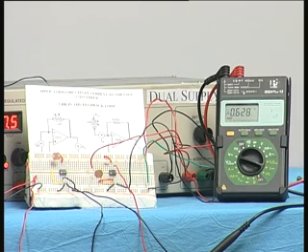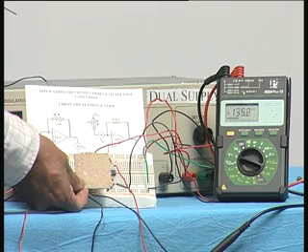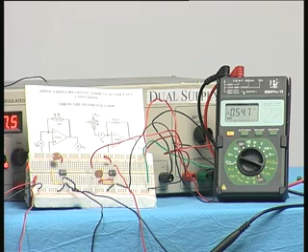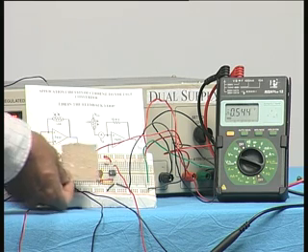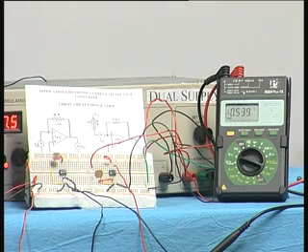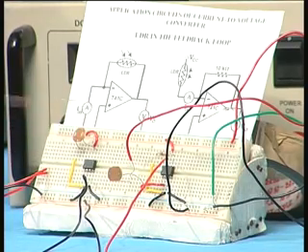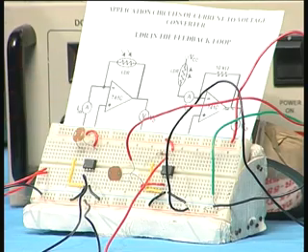Now if I cover the LDR, the resistance will increase, therefore the current will start decreasing because it is forming part of the current source. When I close that, current will decrease, and therefore you would find the output voltage comes to millivolts, 147 or something, 135, etc. So if I remove it, it again comes to 0.5 volts or so, and when I close it, it comes to a few 100 millivolts or so. So you can see this also can be used as an optical detector for detecting light intensity. This LDR can be used by making use of the simple current to voltage converter.